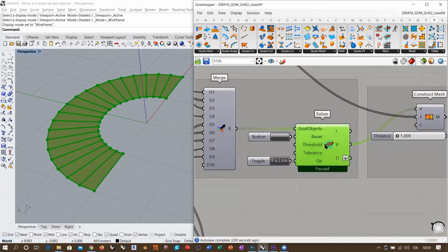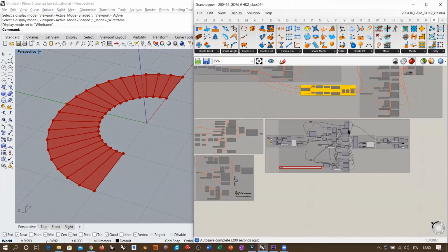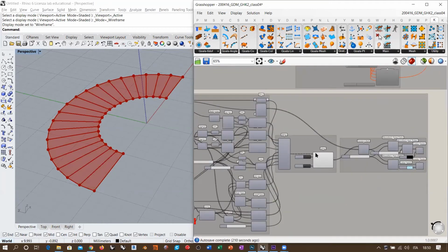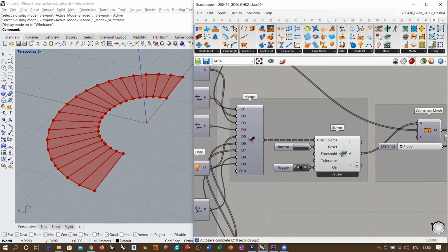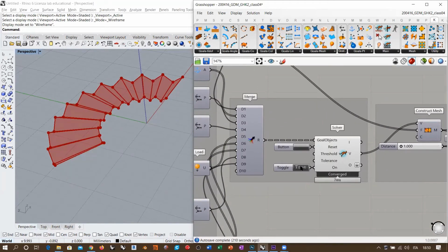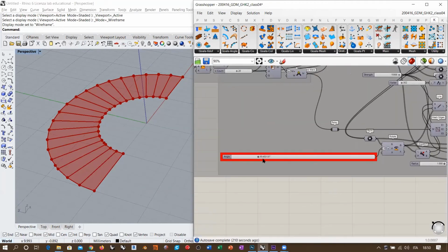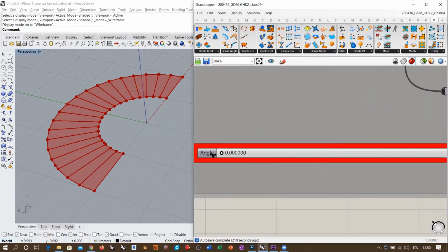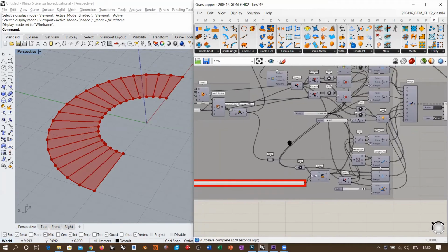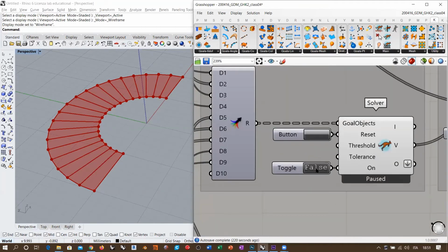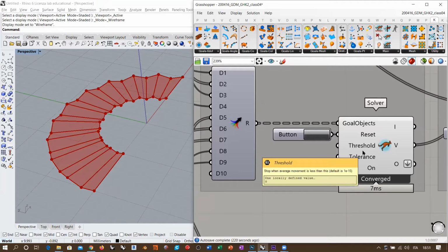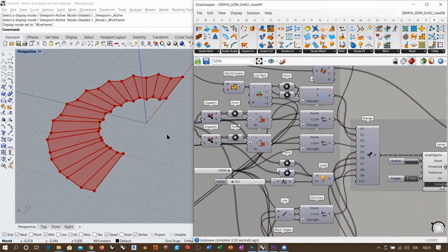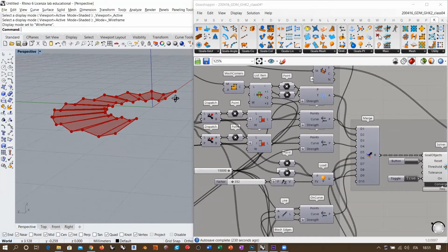Let me turn off everything that's on the left here of Kangaroo. Yep, so we only see the simulation running. And by the way, it's convenient to avoid sudden changes in values when you run this kind of simulation. So here it is, the application of the strength of the load, especially in this case, is already making this structure fall.